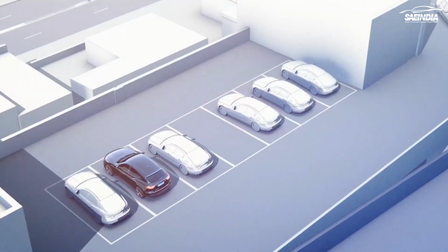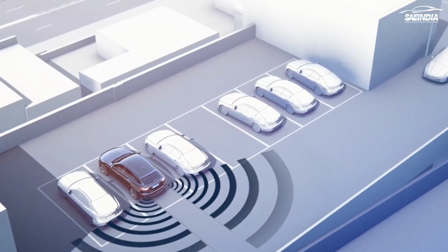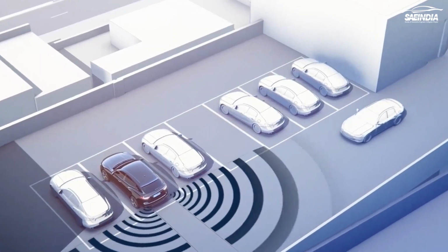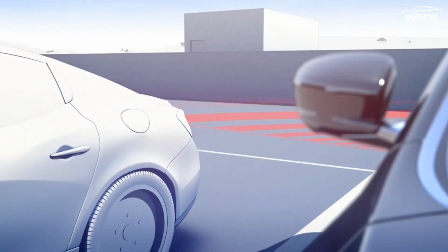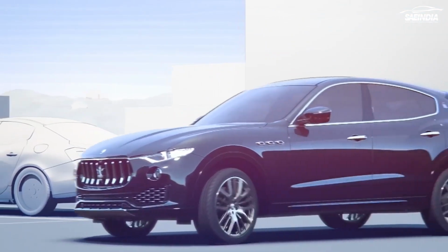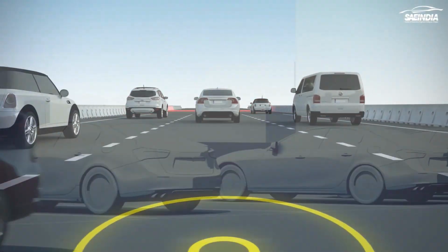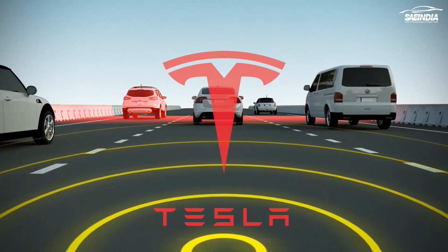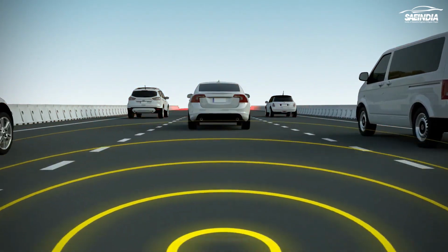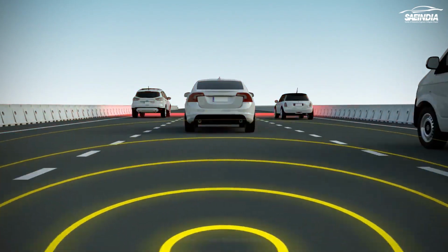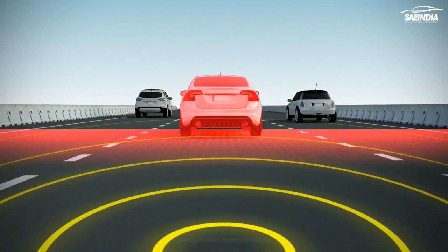Since the sonar sensors operate by moving air and then acoustic reflections, they are ideal for low-speed applications. Because they are acoustic in nature, ultrasound performance can be degraded by exposure to an extremely noisy environment. Interestingly, the electric car company Tesla invented a way to project ultrasonic sound through metal, allowing them to hide the sensors all over the car and maintain vehicle aesthetics.